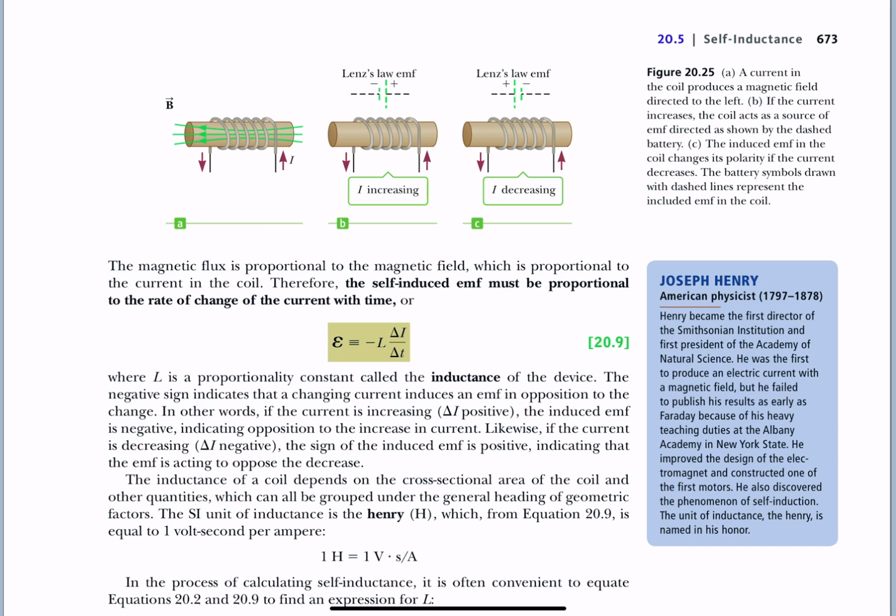And so if you take your right hand in picture A, and you have your fingers following the direction of the current on the right side, going over the bar, and then underneath it's coming back around, and the coil winds to the left, and you've got 3 coils, and then it comes out the bottom on the left side. You'll notice that as your fingers curl over the bar, your thumb is going to be pointing towards the north. So that means you have an electromagnet.